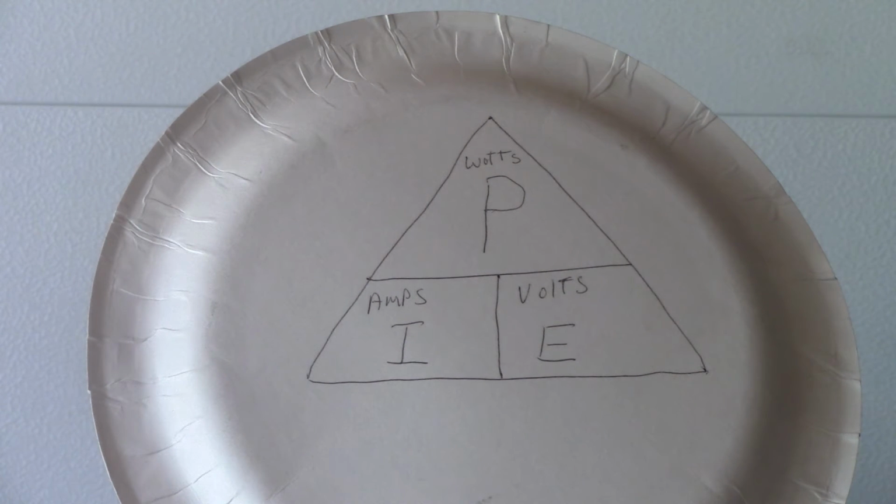Some people are making big mistakes in that area. You have a ratio of 10 to 1 from 120 to 12 volts. So you've got to think that through, and that means your wire size needs to be much bigger. Your fuses obviously need to be much bigger. All that stuff on your DC side. And so that's why I'm showing Watt's Law today. I think it's very important. It would solve a lot of problems.